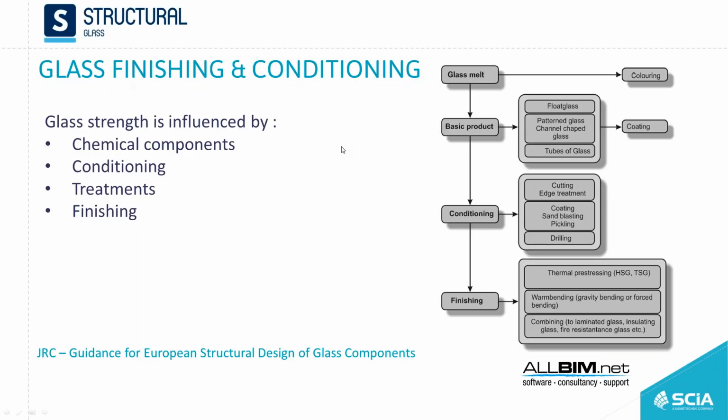This is due to the fact that glass has a thermal treatment that strengthens it, and this will bring some tensions in one of the surfaces. So it's like pretensioning the glass, and that tension gets released when we try to insert an opening. So this is why the production needs to be known, the production process and what treatments are applied. We will see that exactly when I evaluate the strength of the glass. I will change different parameters from a production point of view, and we'll see how the resistance, the capacity of the element, changes.